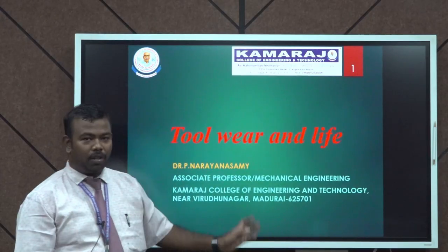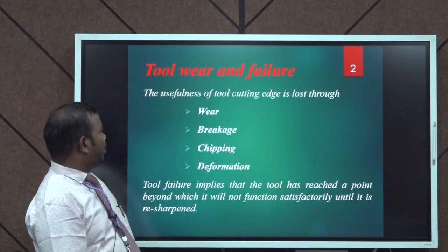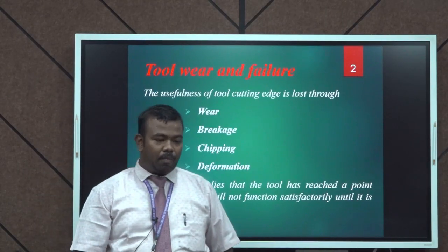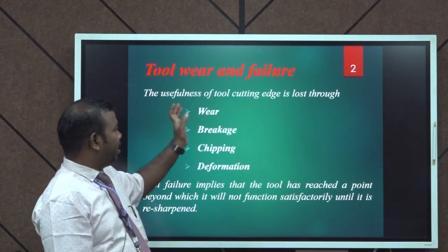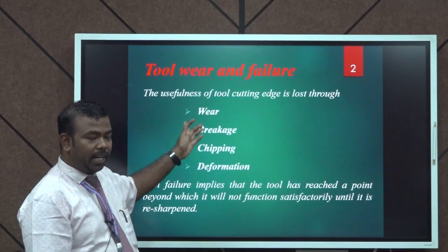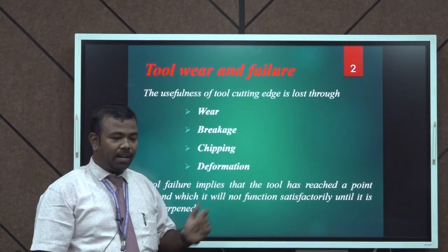Today I would like to explore the topic of tool wear and tool life. Generally, tool failure implies that the tool has reached a point beyond its lifetime. Tool failure occurs on four basic criteria: first is wear, second is breakage, third is chipping, and last is deformation.